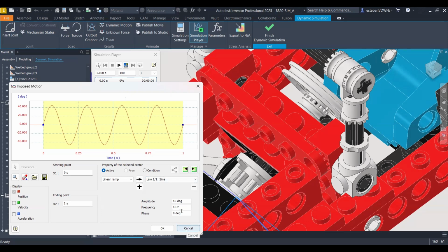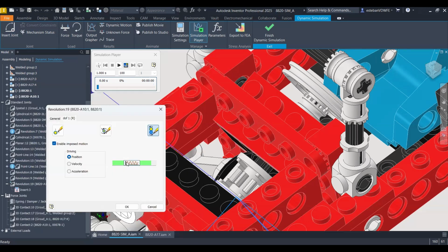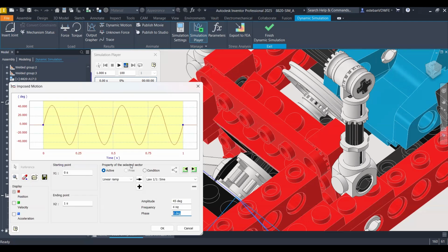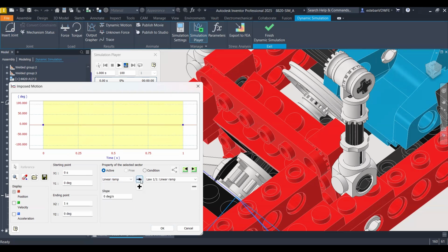And the way to do that is, let me remove this by saying constant value, and now I will click again on the input grapher option. Sorry, it is there. Okay, so how do I delete this? Oh, it's linear ramp. There you go. So when you open this, you are going to have the linear ramp option as the first thing. It depends on just 2 points, and you just apply the degrees from where you want to start and the one that you want to finish, and the time is going to give you a slope.